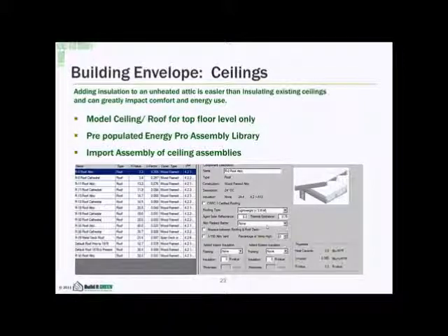If you have a radiant barrier, you're going to have a drop down and select the different types. There's continuous, and there's continuous with skip sheathing, I believe. And if you are modeling this per Title 24, Title 24 asks that when you install a radiant barrier that you also add an airspace and do the 1 in 150 attic vent and have a 30% high roof.